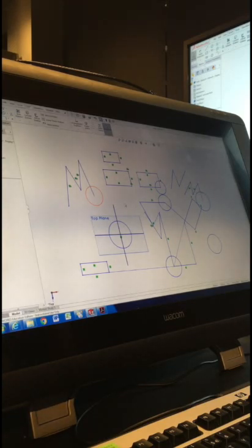So when I'm talking about fully defining a sketch, it means that all the lines, all the circles, they know where they are supposed to be in that sketch. They know their dimension, they know their radius, okay? And they also may need to know if they're a horizontal line or a vertical line or parallel. To fully define a sketch, you need a combination of relations and dimensions. Okay, we haven't done any dimensions yet, but these are just relations you can see on screen.